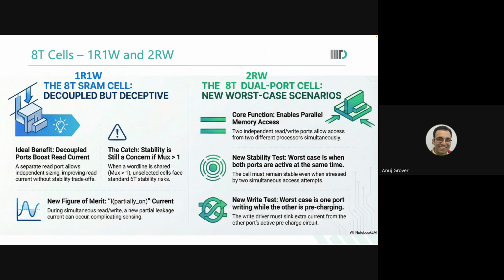So your particular cell through which you are reading would be in read mode on the 6T port side. So there will be a Vx that is generated. That Vx will turn on the read stack a little. So there is some more current that is going to flow than just the leakage current. If this current is very large, then add leakage to it, your reading operation may fail. Are you with me on this?